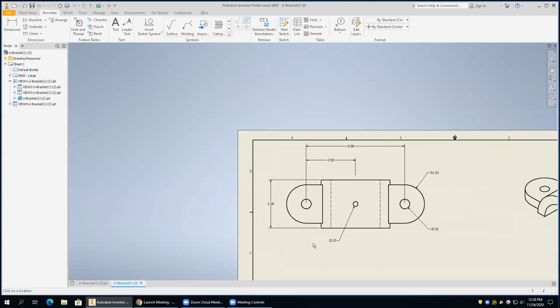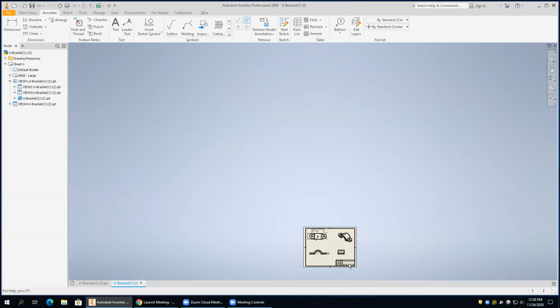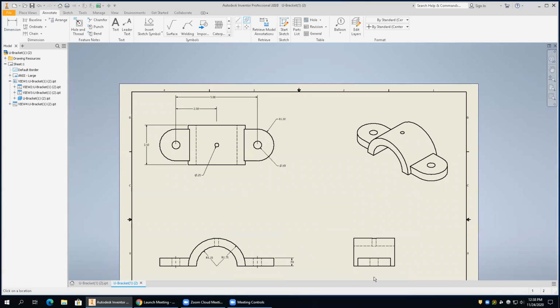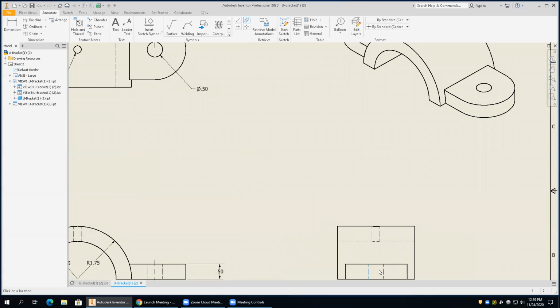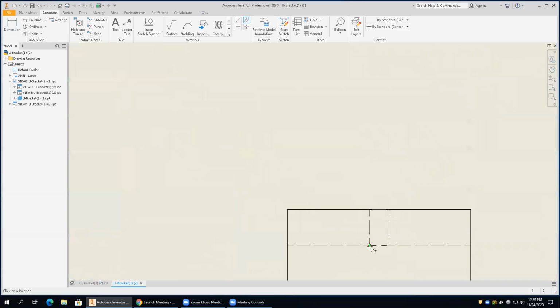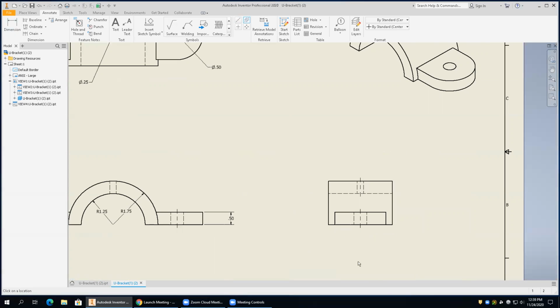We technically want bisectors in some other places. We'll handle that with some other things. I think we've got all the bisectors that we need right now, so I think we're good. You guys getting that tool to work? Actually, there should be a center line bisector here on that one, and there should be a center line bisector here. Okay? Does everybody get that to work? So those are showing the center line locations of where those holes would be.